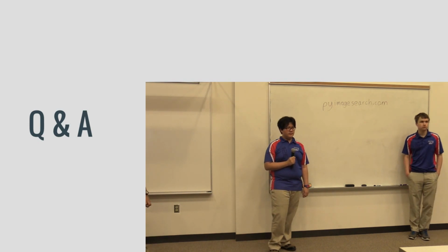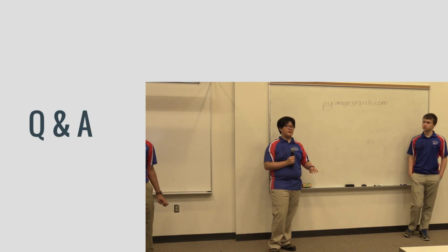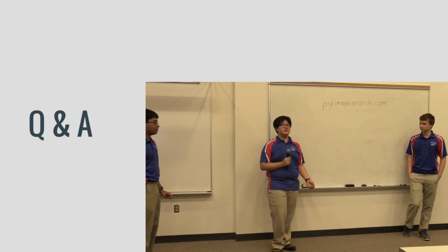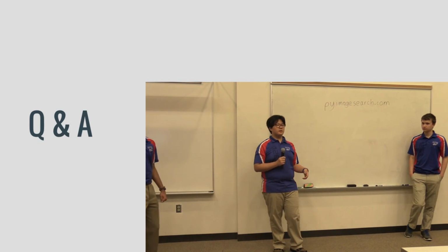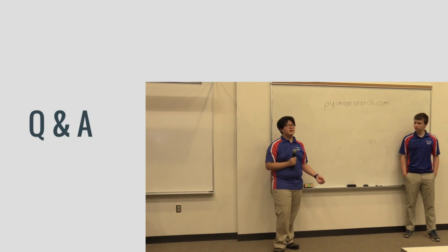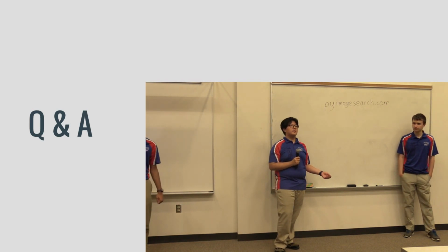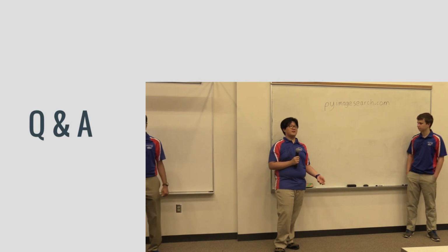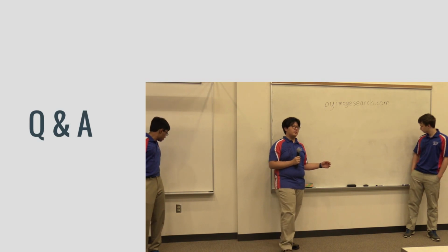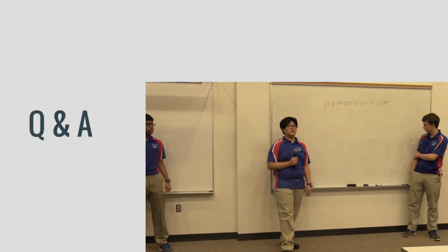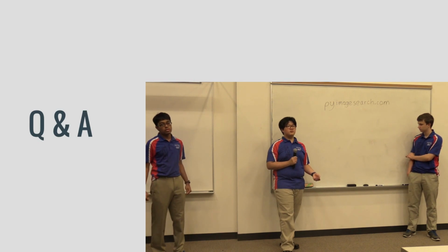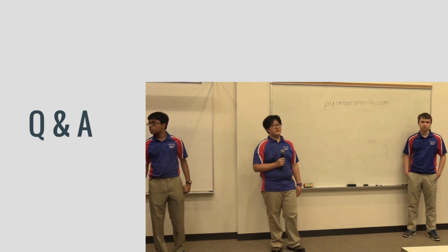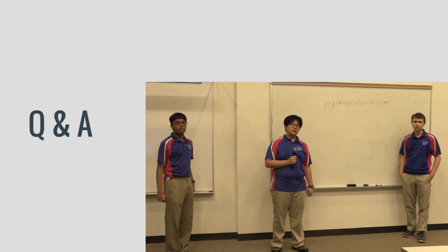This process is a lot more mitigated now because the Raspberry Pi 3 came out. The Raspberry Pi 3 is way faster than the Raspberry Pi 2. I tested it personally at home with my Raspberry Pi 3 using our own code, and it actually ran way faster, especially since the Raspberry Pi 3 has 4 cores on it. Our old code would only take up 25% of the processing power of the Raspberry Pi 3, while the Raspberry Pi 2 had to use the full 100%. So you could do a lot of multi-core processing with the Raspberry Pi 3 to drastically improve performance.